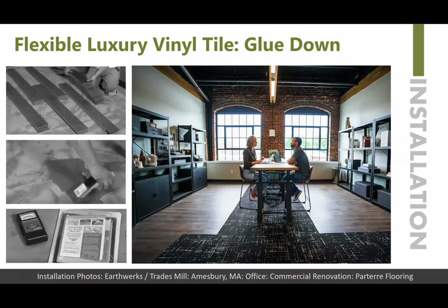Glue down installation methods involve the use of an adhesive to adhere your dryback luxury vinyl flooring to the subfloor. Using adhesive creates dimensional stability that ensures the flooring maintains its natural characteristics. The glue down method includes 2 distinct types of adhesive, hard set and pressure sensitive. Hard set is adhesive spread along on the floor, then the flooring is laid on top. Pressure sensitive is the flooring product has adhesive on it and it is bonded to the substrate with pressure.